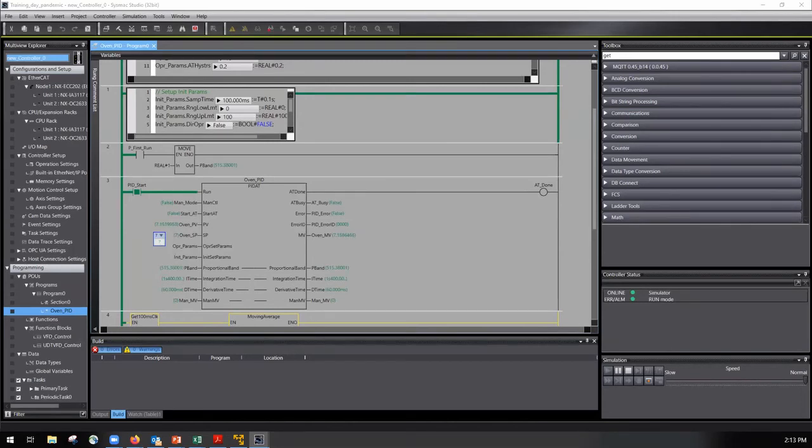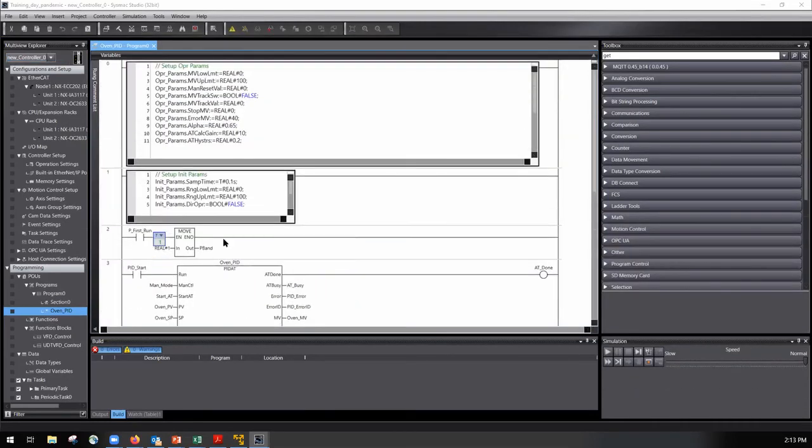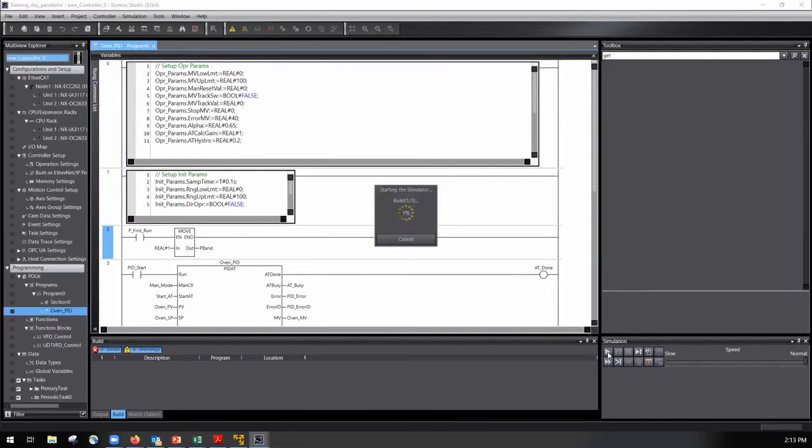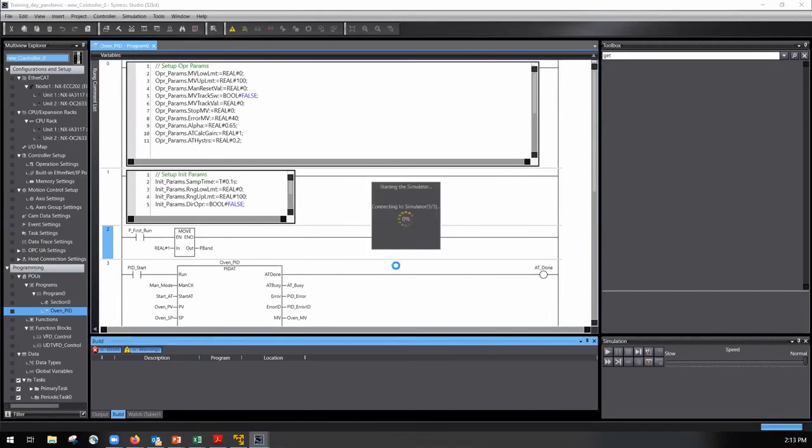I was going to show, and you guys don't need to play along with this, but like I said, the one thing I want you to remember about auto tuning these things is this calcgain. So that was 10, right? That's very smooth, very slow to react. By default, it's really quick. So I'm going to make that 1, and I'm going to rerun this simulation. And it's probably going to be too reactive to even auto tune.